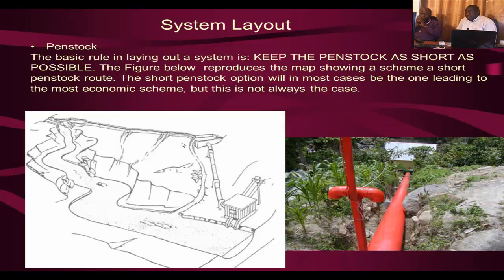Let's look at the system layout of a small hydropower scheme. Penstocks. The basic rule in designing any hydro scheme is to keep the penstocks as short as possible. Short penstocks will normally lead to the most economic scheme, but this is not always the case.